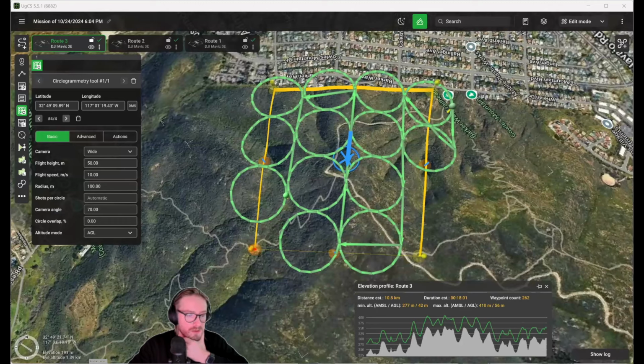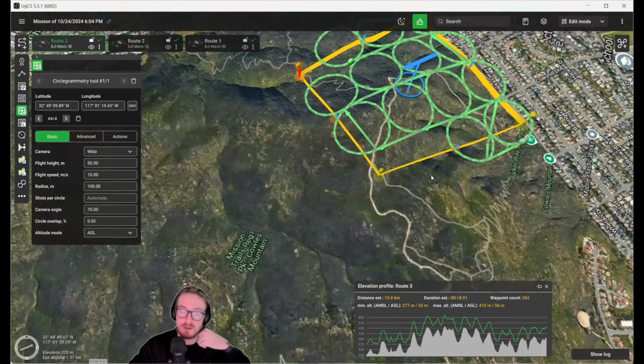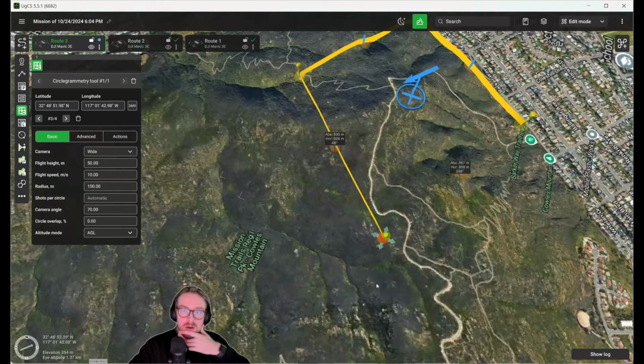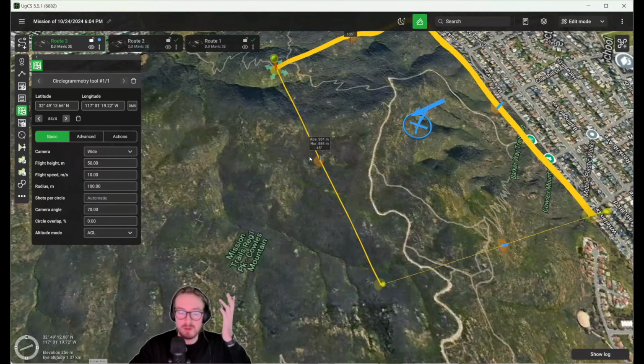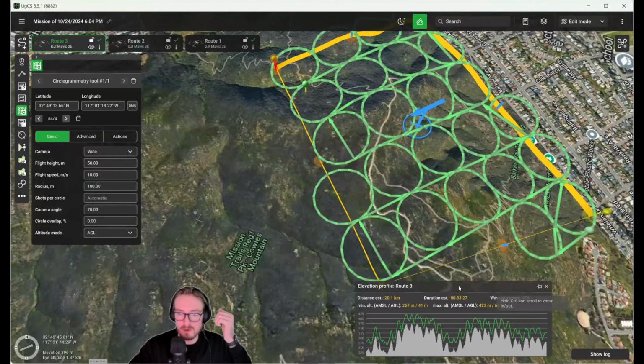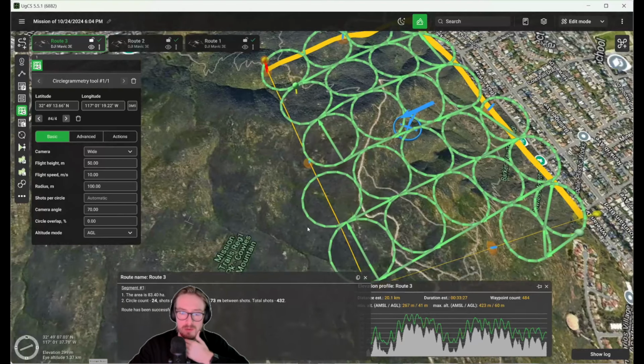And that's another from Randall. It's about search and rescue: 10,000 to 14,000 feet, steep terrain, locating lost, injured people. Oh, that's actually also really interesting. I guess if you need to scan a large area, then instead of flying in a grid, you can also fly in this pattern. Just select a very large area and set the flight time to something like 30 minutes. You can see, for example, this whole area, and we should be able to see the size of it if we go in here. So yeah, 83 hectares that you would be able to cover in about half an hour if you fly like this.